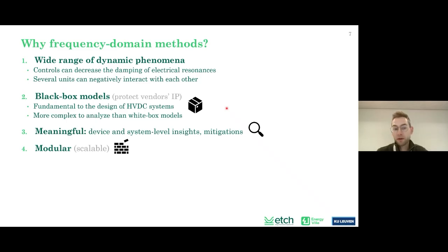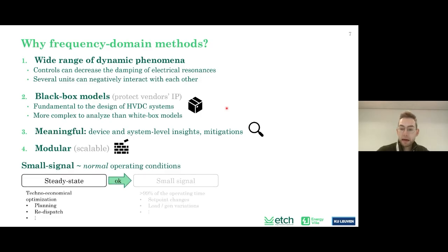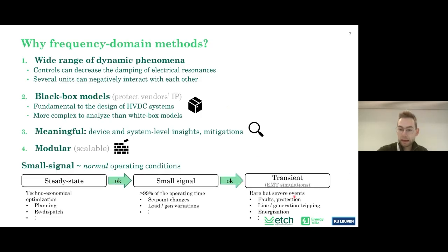Frequency domain itself is very modular and scalable. So you can aggregate buses in the system, which you will see in an example I've prepared for today. And then small signal is the underlying cause of the oscillations. I mentioned that. And the system is operating in the small signal regime most of the time. So it makes pretty much sense to evaluate the equilibrium of the system in order to assess the stability of the system. And this can be nicely done in the frequency domain.